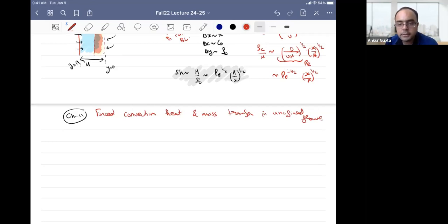All right. So physically, what do you think is the downside of unconfined flows? Confined flows are nice in a way that you only have one velocity. But when you start to think of unconfined flows, flows around a sphere, flows around a cylinder, you can imagine that now we'll start to have bidirectional flows. We'll have multiple directions coming in, complicating our analysis. So that's why unconfined flows are generally taught later.